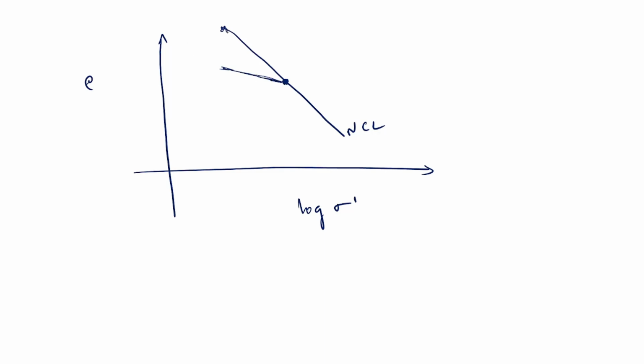Suppose this was the starting point, and it has gone up to here. Then you are removing the load. You might think it should go back along this same line, but that's not right, because there is some elastic settlement and some plastic settlement. The plastic settlement will not rebound. Only the elastic compression, or elastic change in void ratio, will go back to here. It will swell. That's why this portion is called the swelling portion.